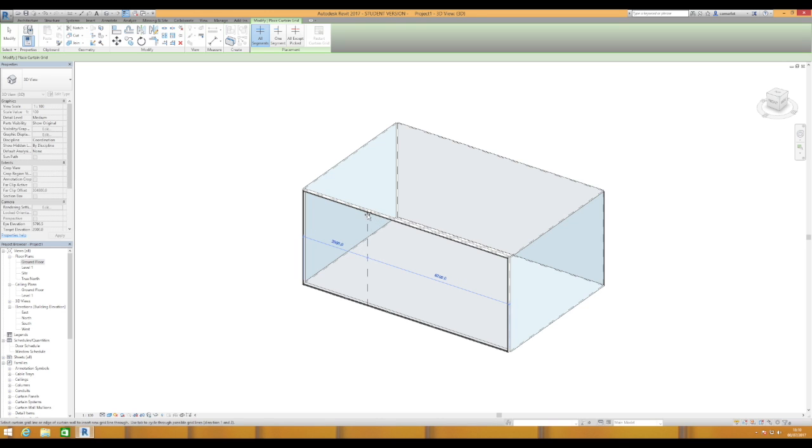So if I was to divide this up into thirds initially, and then the leftover piece that's left here, I can divide that into half, so we've now got 3 equals. And then if I was to divide each of those others into 3 also, I'm getting 1 meter sections through here now, and it makes it very easy in Revit to create those even divisions.